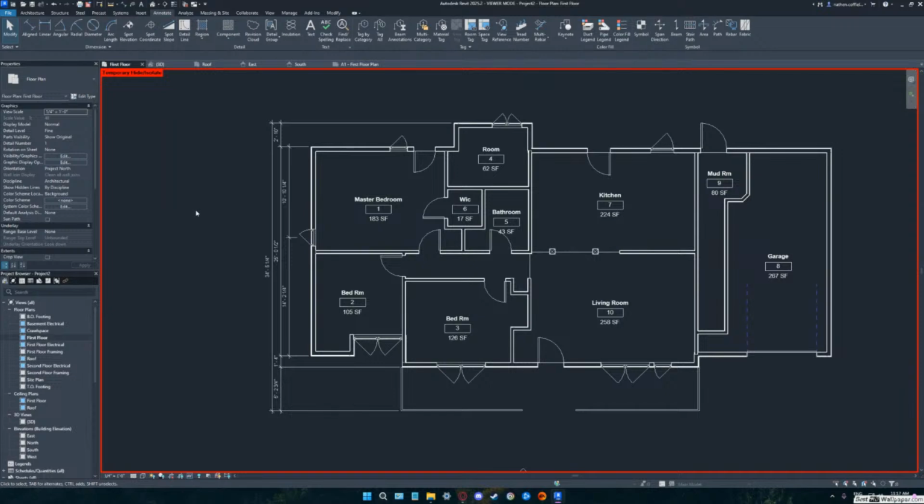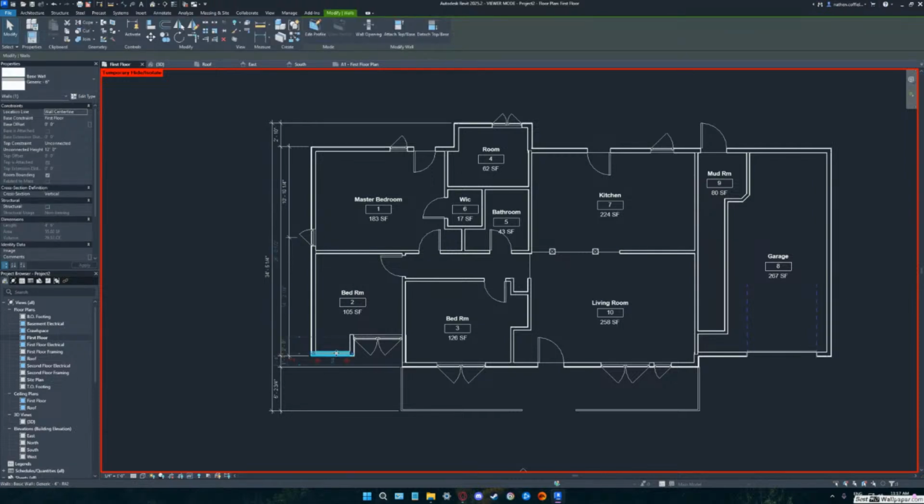So that one in bedroom number 2, the wall that we've dimensioned, pick that wall. This one right here? Uh-huh. Okay. You see how all your dimensions got a little bit of blue to them? These? Yep. So that 25 foot 0.5, I would probably make that 25. Just type in 25 and hit enter.